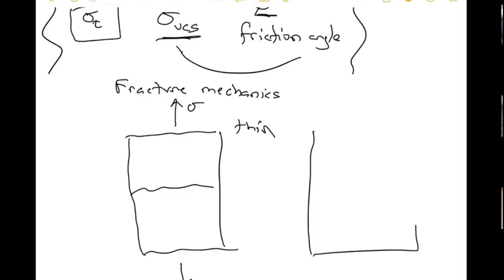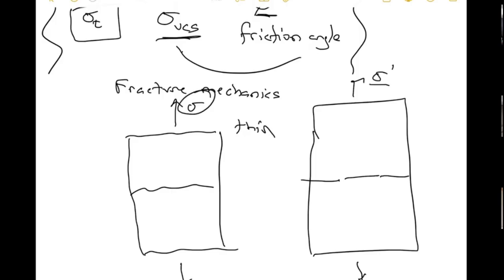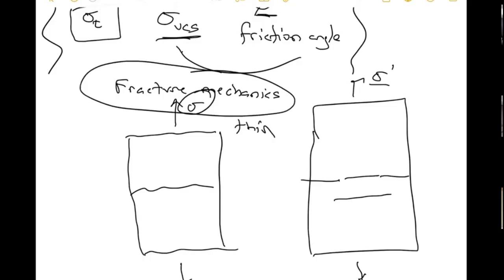But if you take that same piece of paper, take out your pocket knife and put a slit in it, and now you pull it, at some point, nothing's going to happen, and then boom, it's going to rupture across there. And this value is significantly less than this value. And if you do the same test and put a longer crack in it, it's going to be even weaker. It turns out that fracture mechanics is studying this whole process: how does a material get weakened in the presence of a crack? A crack has a giant effect on strength because it's a super weak point.